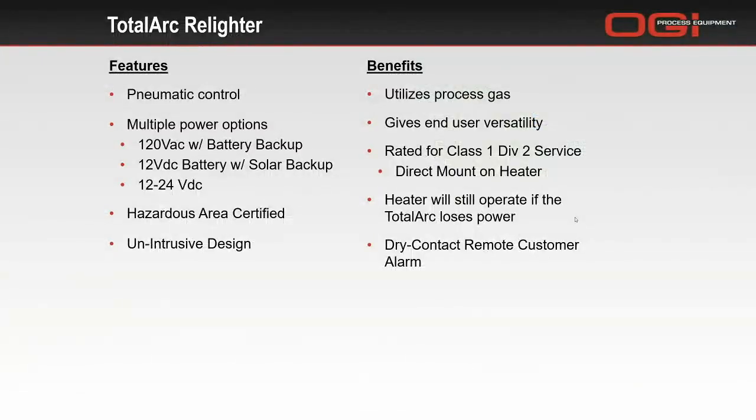Some of the features that the TotalArc Relighter has is, of course, as we mentioned before, it works in conjunction with a pneumatic flame safeguard. The power options that we offer on the TotalArc Relighter: it's 120 volts, and that comes with a battery backup to maintain the operation of the TotalArc Relighter even when power goes out. We also have an option for a solar system that has a 12-volt battery inside of it, and it will maintain the operation of your TotalArc Relighter for a period of 7 days, and that is without solar power.